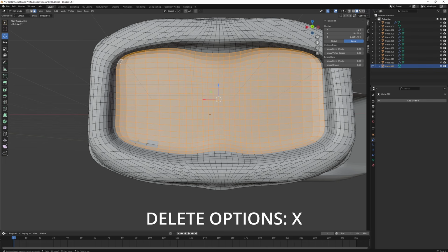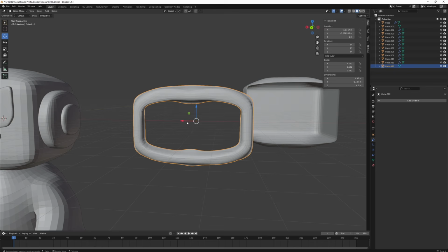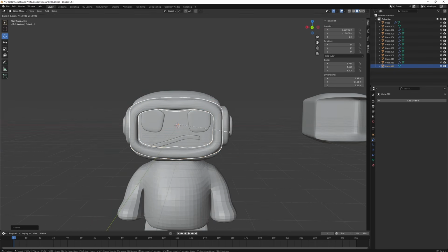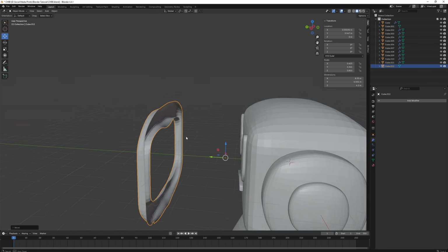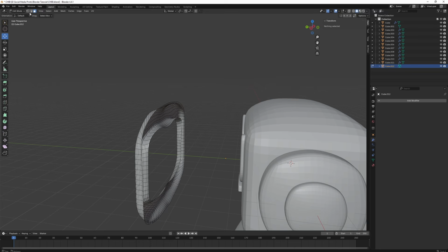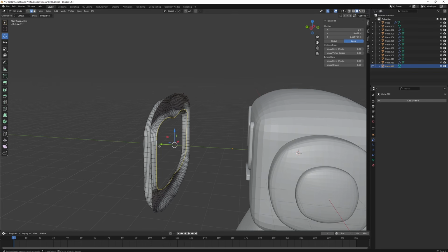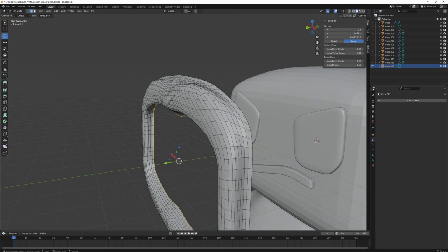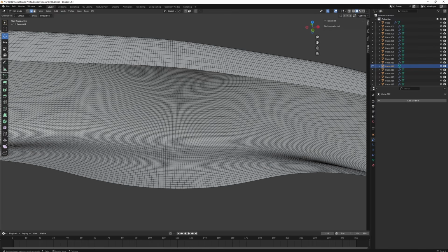We now have a frame and we can drag it over to the original shape and scale it as you wish. You might notice that this has a big hole on one side where we separated it. We need to close this. It's an incomplete mesh and any gaps in meshes are not printable. To close meshes with more than one loop, simply select an edge on one loop and another on the other loop. Press F to fill and it will create a face joining them. This has made both loops into a single continuous loop.